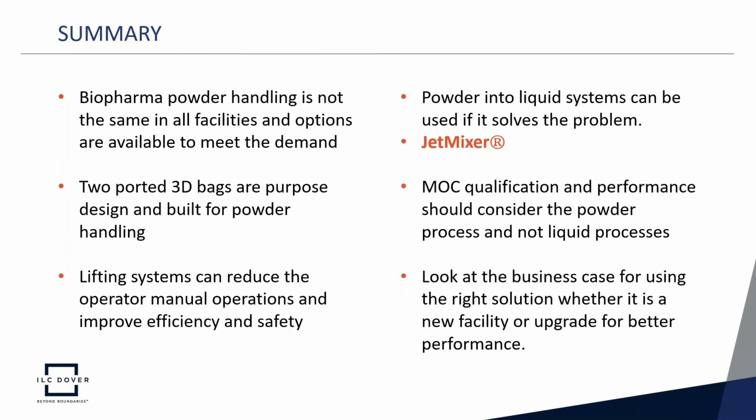So in summary, taking a look at our presentation today, we see that biopharma powder handling is not the same in all facilities, and so there need to be options available to meet the demands of each facility. The two-ported 3D bags are purpose designed and built for powder handling. The 2D single-ported bags seem to be a migration from liquid handling into powder handling, but here we have the 3D two-ported bag really for these media and buffer applications. Applying lifting systems and transfer carts can improve the operator manual operations and improve efficiency and safety.